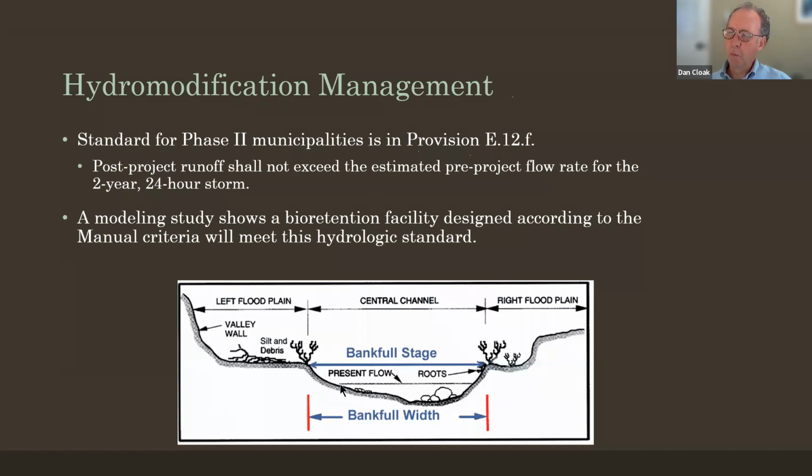Can cause erosion of the stream banks, because the whole time that they're running at that level, you have the potential to begin moving sediment. Even though those flows are not particularly turbulent or rushing, the amount of stress that they put on the stream banks over time will break off pieces of sediment, and they will move downstream. Over time you get downcutting and widening of your creek banks, and pretty soon you have something that looks more like an urban stream, which does not have the same biological value as streams that are unaffected.